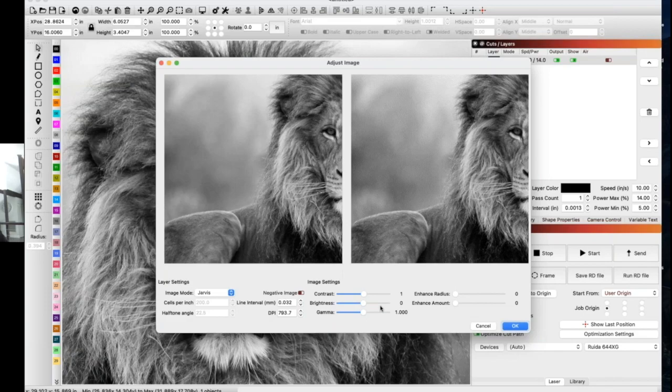So I heard some people say that our numbers are not right, and that's what it says on our site, it's 5 to 6.5 millimeters. We say 6 millimeters, but it may be a little off. And they could use that test in LightBurn, if they're comfortable moving the Z-axis a little bit, doing the focus test.